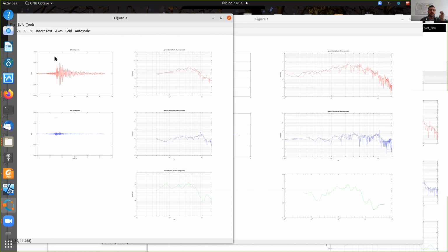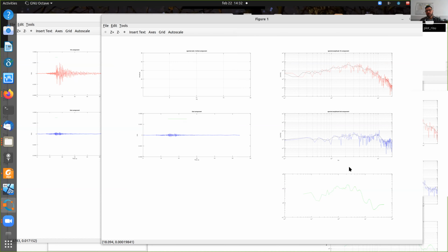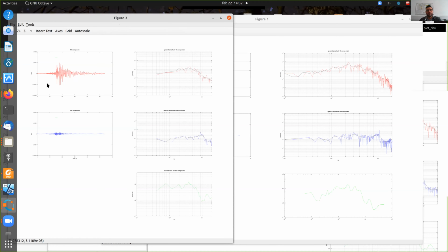Here we are closer to the S wave phase, but we don't have enough resolution to see the resonance frequency of S waves, because it's a lower frequency than what we can see. If we then try to solve the problem by enlarging the window, of course we can have a site response which is more broadband, but we are not only considering the effect on the S waves, but on the overall signal, of all the phases arriving also later. So this is the compromise that we are always paying.